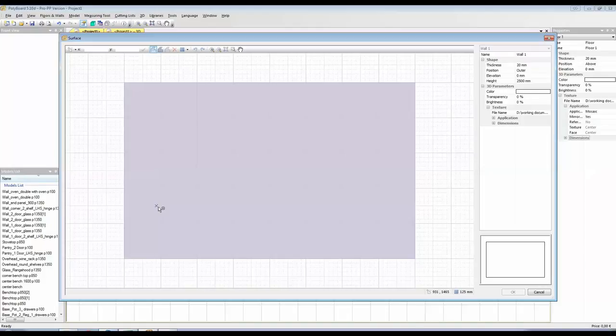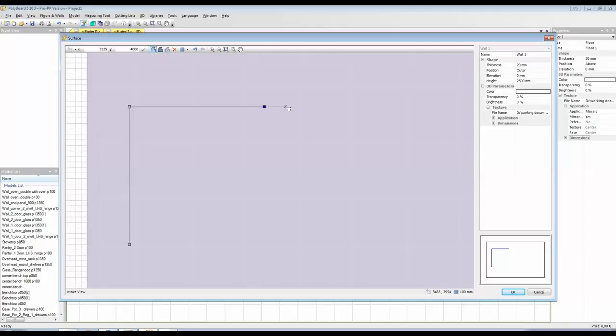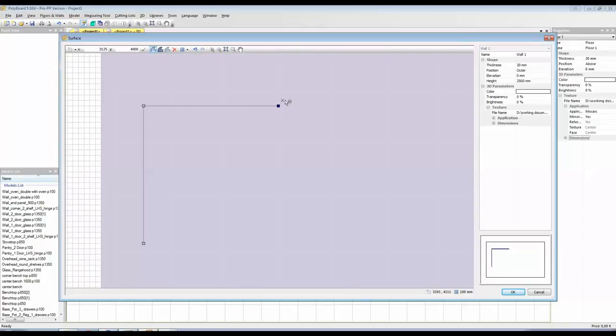To add a wall, we just click points around, and it'd be exactly like drawing the polygon, the floor surfaces, that is. And as we draw, we can see that there is a little shaded area that will appear on one side of the line. This shaded area, as we are drawing, represents the wall, and its properties are in the right hand side properties window.